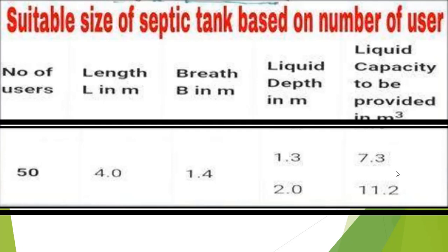Base of the septic tank for better extraction of the sludge at the time of removing sludge. Also, the floor of the septic tank should be given a little slope of 1:15 towards the inlet side. Fourth, the width of the septic tank should not be less than 750 mm. Fifth, the length should be 2 to 4 times the width of the septic tank.